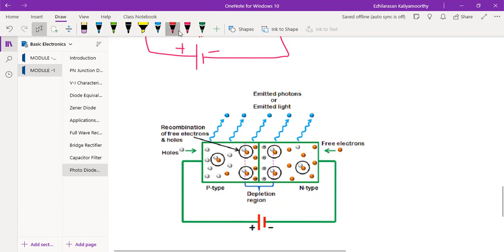You see here, which is shown here, that is a recombination of your electrons and the holes, recombination of free electrons and the holes that will emit the light, or it will emit the photons. So even here also in the p type. Here you can see in this figure clearly we mentioned. But here the process of emitting light in response to the strong electric field or flow of electric current is called electroluminescence.